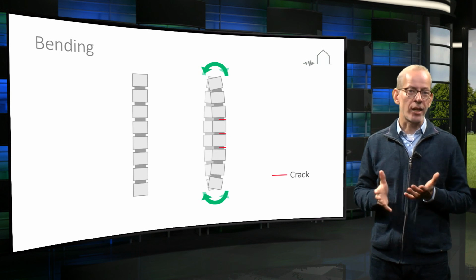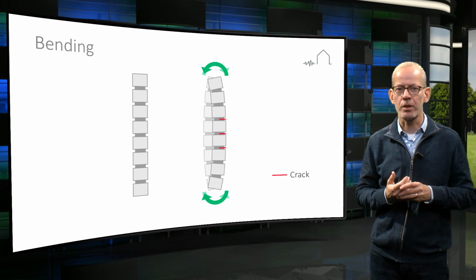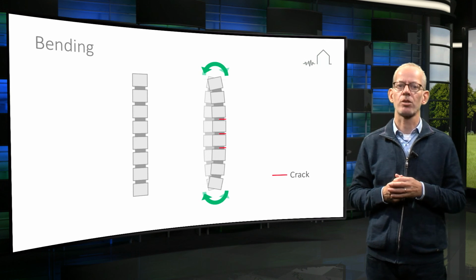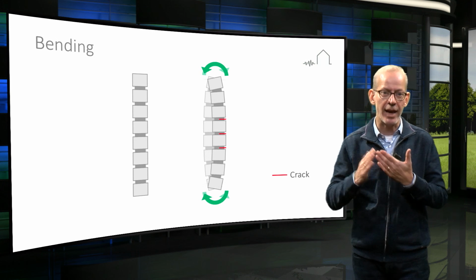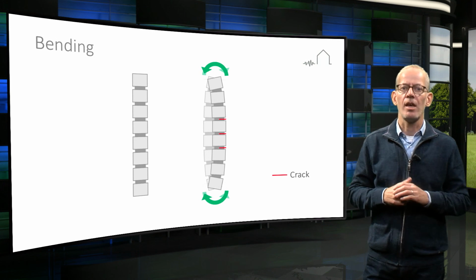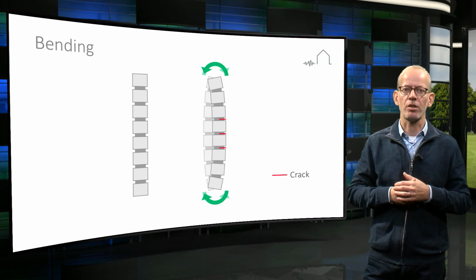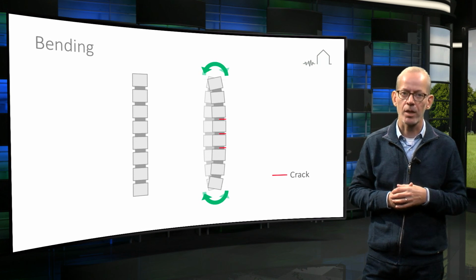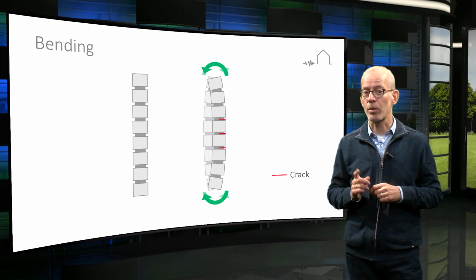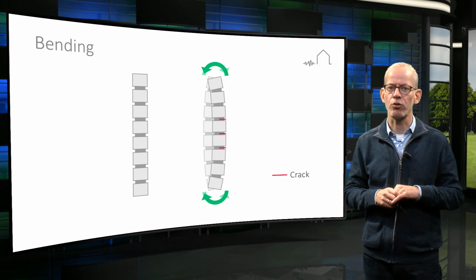So, in this lecture we have seen how masonry can respond to earthquake accelerations. We learned that this response can be divided in in-plane and out-of-plane direction, and various material properties need to be determined in order to predict the safety. In the next lecture we will see some of the experiments used for this determination.